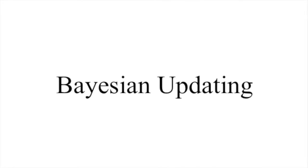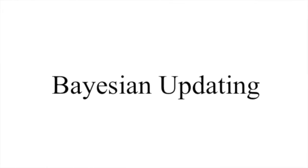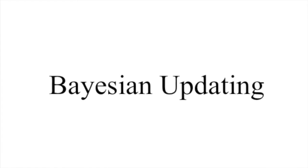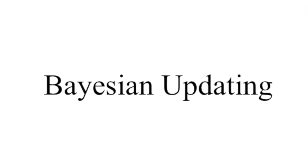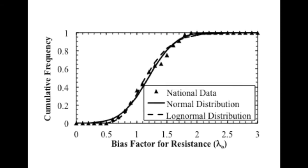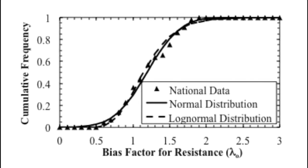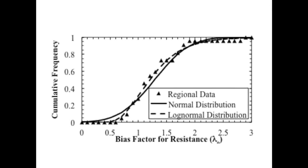Bayesian updating is a technique that is commonly utilized to make inference of a given limited dataset by utilizing a larger dataset. For the case of the TRC 1204 project, the larger dataset came from 2 different sources. These sources were a national dataset that was published by Paikowski in 2004 and a regional dataset that was published by Abu Farsak et al. in 2010. The national dataset should be modeled as being normally distributed, but the regional dataset can be modeled as being normally or log-normally distributed.